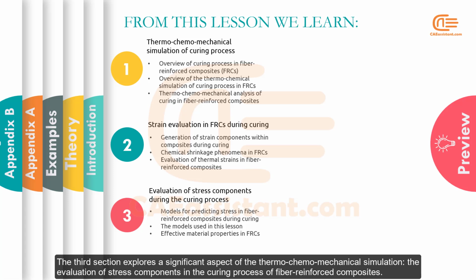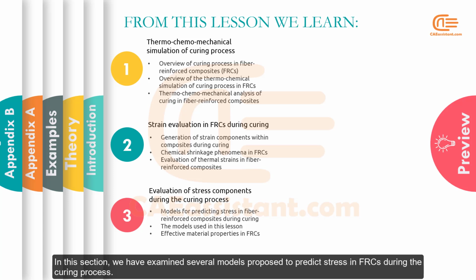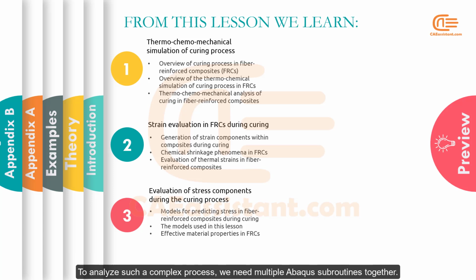The third section explores a significant aspect of the thermo-chemo-mechanical simulation, the evaluation of stress components in the curing process of fiber-reinforced composites. In this section, we examine several models proposed to predict stress in FRCs during the curing process. Following that, we provide information on the specific models used in this lesson and explain why they were chosen. To analyze such a complex process, we need multiple Abaqus subroutines together.